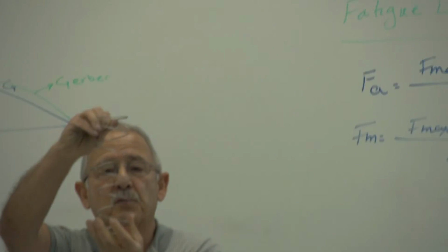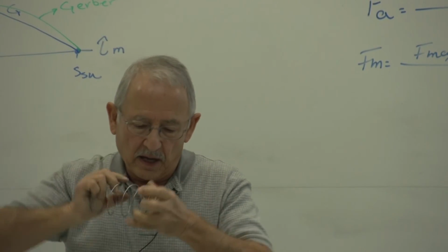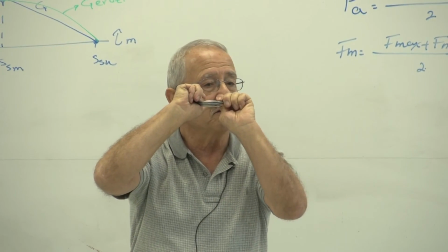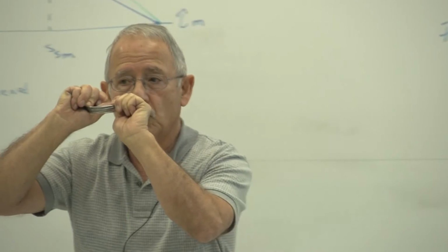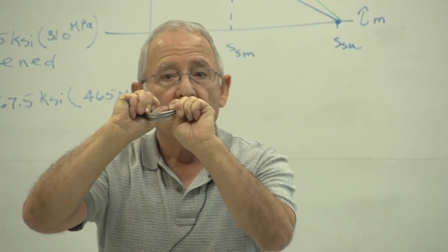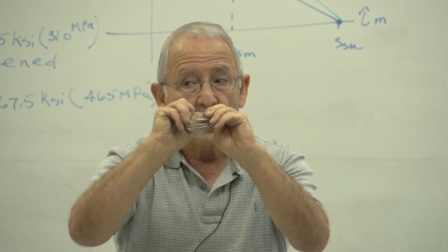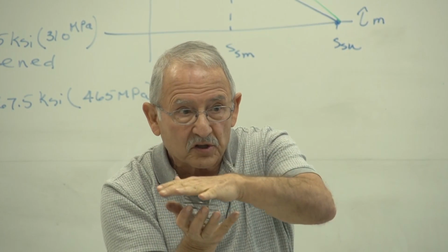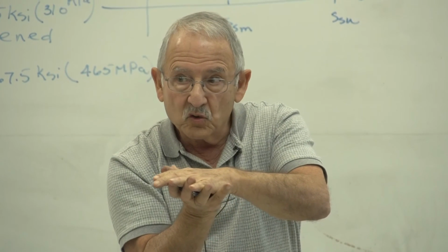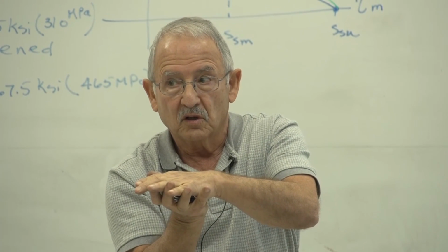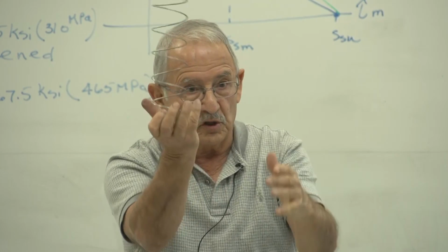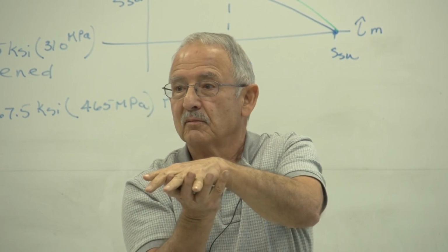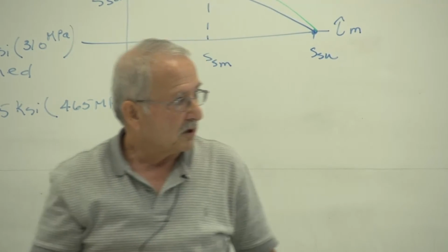You have this spring, and that's more or less the solid length of the spring. Okay? All coils are in contact with one another. What I would like to find out is what force is required to bring this to solid length, and then use that force to find the stress. That force is equal to the spring constant multiplied by this deflection. So that's what we're doing here.